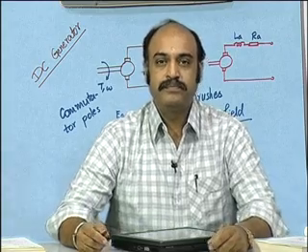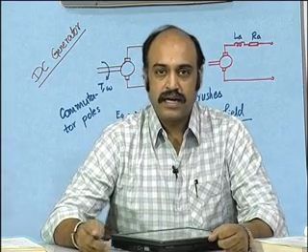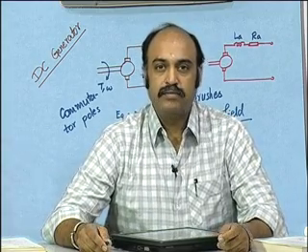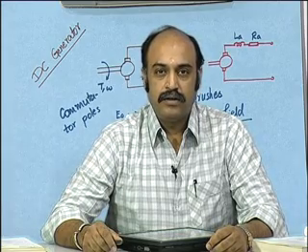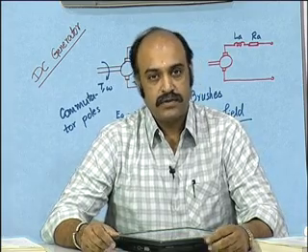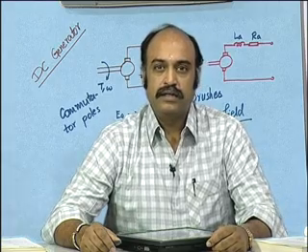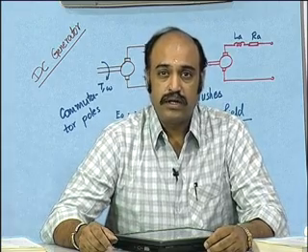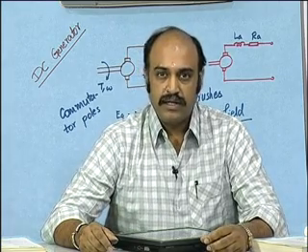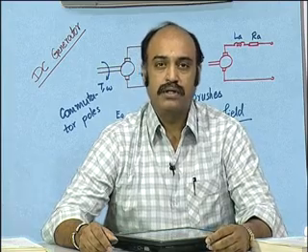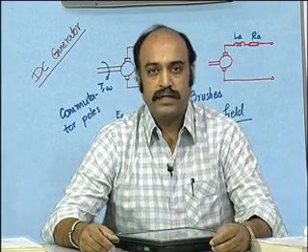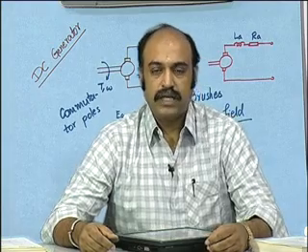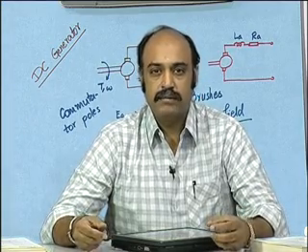Hello everybody. So in the last class we were discussing the DC generator, mainly the structure of the generator, the way the commutator poles are segmented, and the way the brushes are positioned in the neutral zone, so as to get an output that is ripple free, that is, containing as little ripple as possible.